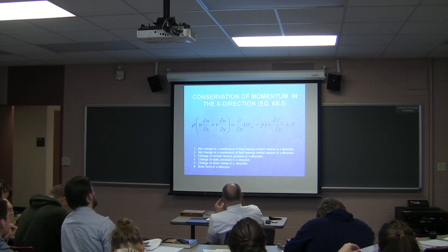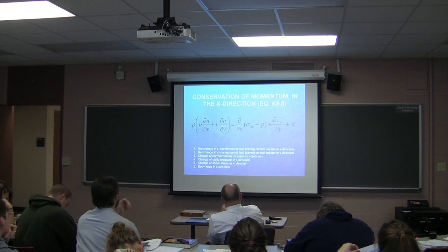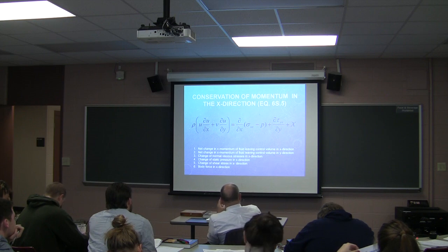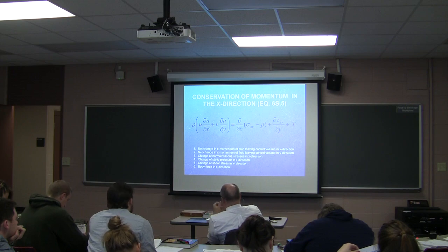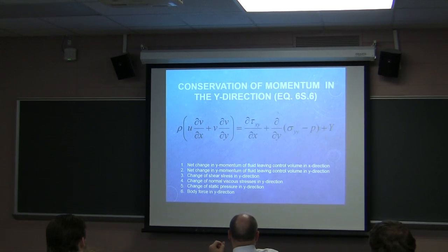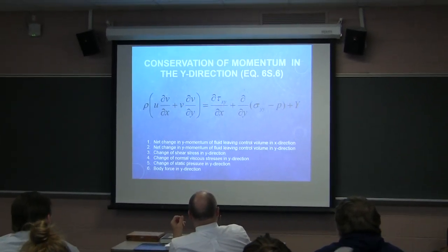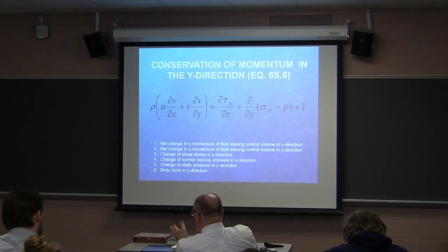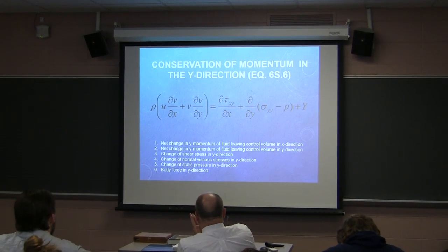Then we have the change of the normal viscous stresses in the x direction, change of the static pressure in the x direction, then the shear stress changes in the x direction, and lastly the body force in the x direction. That's the big piece. Then the y direction is identical to that, except with everything with respect to the y direction.